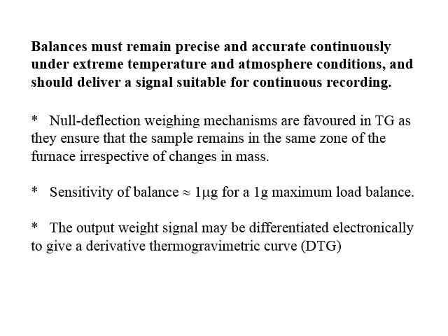So you want something that measures the deflection and then either compensates for it or measures the force as a change of the weight. Because if the sample actually moves up and down in the furnace zone, there can be changes in buoyancies from the gas, and there also can be changes in the actual temperatures. There could be a temperature gradient within the furnace. So in general, in a TGA system, a null deflection device is preferred because it maintains the sample position in the furnace.